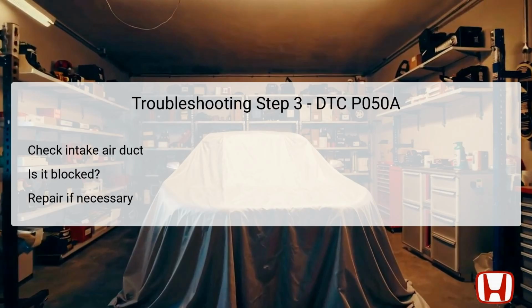The next step requires checking the intake air duct's condition to ensure it is neither blocked nor incorrectly installed. A clear path is vital for proper air intake, especially during cold start conditions, where optimal airflow is critical. If you find that the duct is indeed blocked, it must be repaired or replaced to guarantee that air can move freely into the engine.